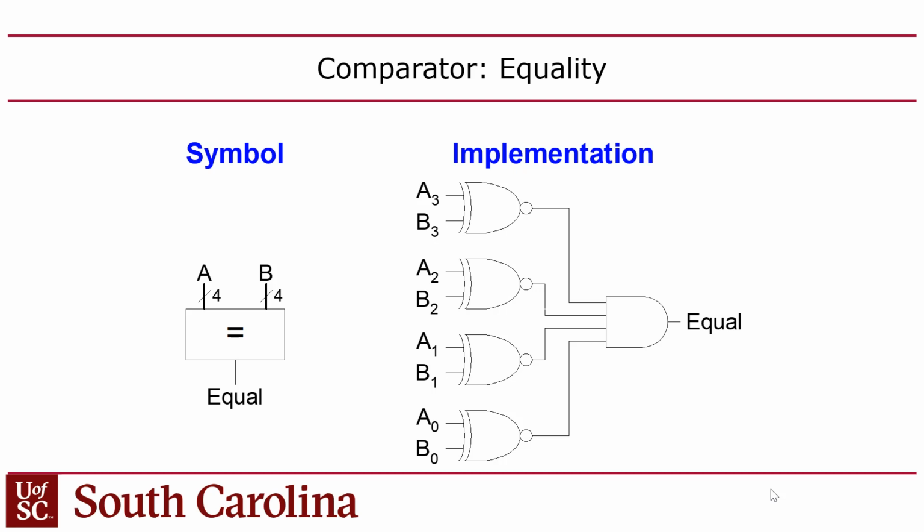So you may have 5 stages of ANDing in practice, maybe not on an FPGA because you have 6-input LUTs. But either way, this is the hard, expensive part of a comparator.